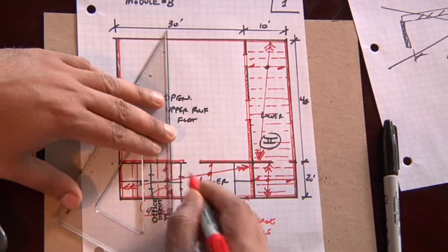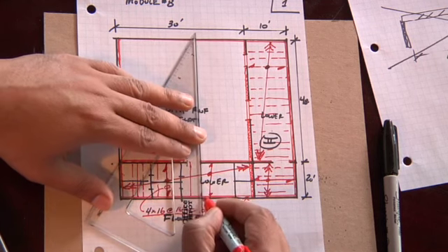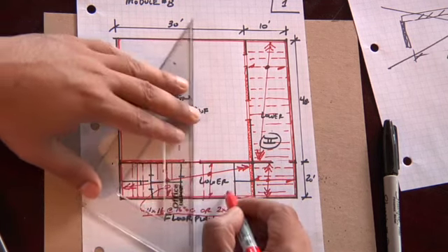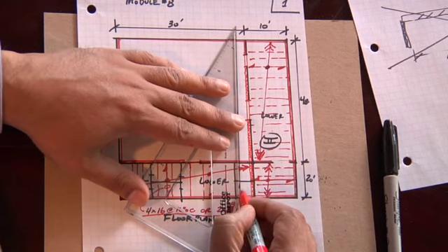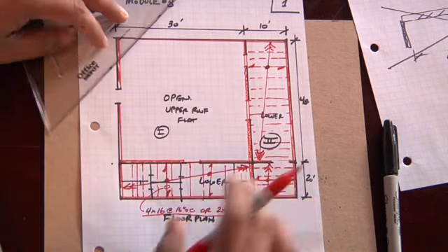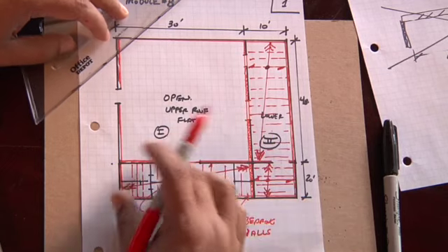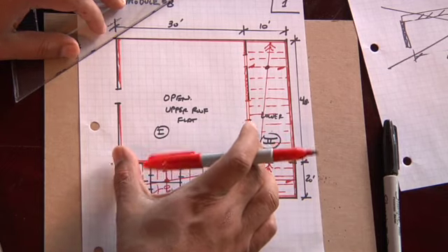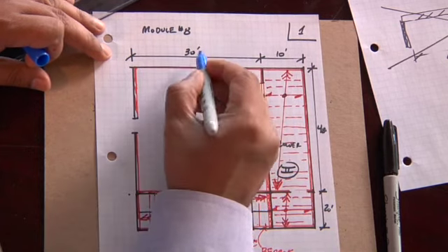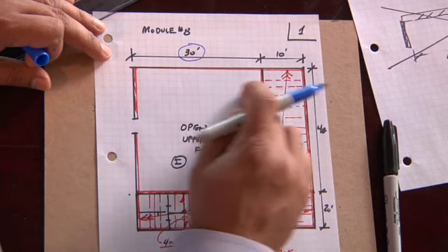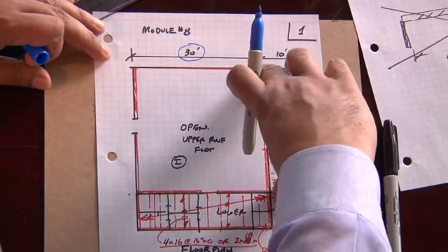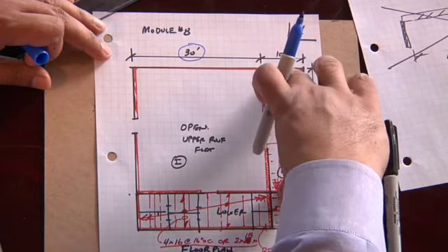Okay, so now we've solved. Here you're going to have a header running across. So now we've done the layout for the lower roof. For the upper roof, again, using the same judgment, we have two numbers here. I'm going to shift the color of the pen to talk about the upper roof. So for the upper roof, we have a 30-foot span in one direction. We have a 48-foot span on the other direction. The drawing's not drawn exactly to scale.